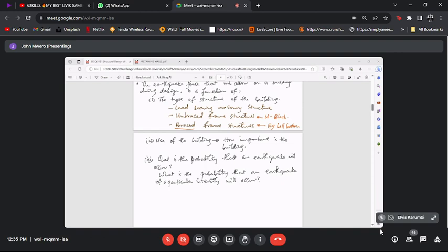But that's the thought, that we want to load a 1 meter width strip of the wall, analyze that, design that, and then just replicate whatever specification we found for the entire length of wall, just the way we do for slabs.